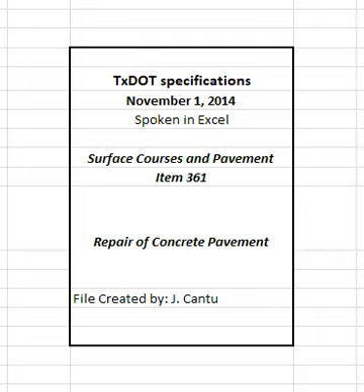Provide Class E concrete designed to attain a minimum average flexural strength of 255 psi or a minimum average compressive strength of 1800 psi within the designated time frame if the time frame designated for opening to traffic is less than 72 HR after concrete placement. Otherwise, provide Class P concrete conforming to Item 360, concrete pavement.